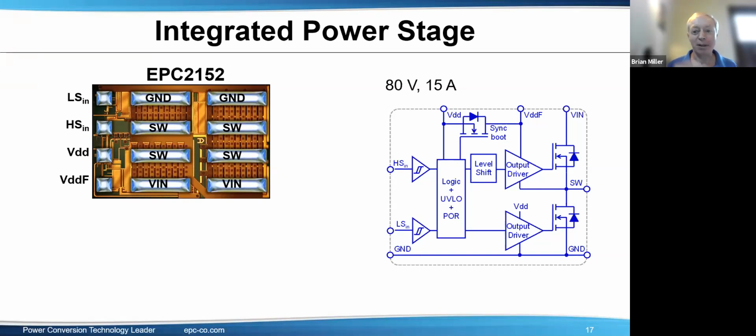You take the little one that was used for the bootstrap, my goodness, just very fast. And we thought there was a certain speed. And then TI came out with a really good single gate driver, the LMG1020, that just pushed it further. So it's mostly due to external factors as far as delay time, with, say, drive resistor and parts. It sounds like an evasive answer, but it's really not. It depends so much on external things.